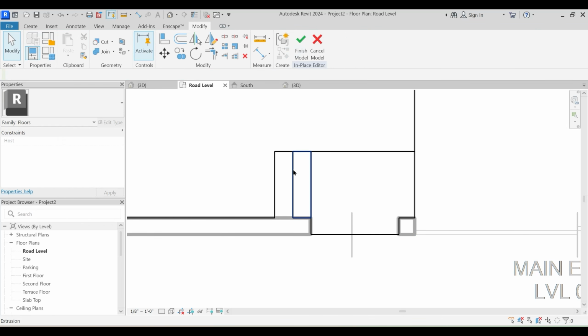Okay, and ramp 2, and go to edit type. Now herein you would say that the shape you want is that the solid. Okay, and this is what is this. So these two factors are very important to understand the ramp. Okay, so maximum incline length is 30 feet. So that means the unit distance you travel in X direction is the maximum incline length. So in this case, let's measure this. It's 10 foot and 11 inches. Fine. So let's go to edit type, and this would be 10 foot 11 inches.